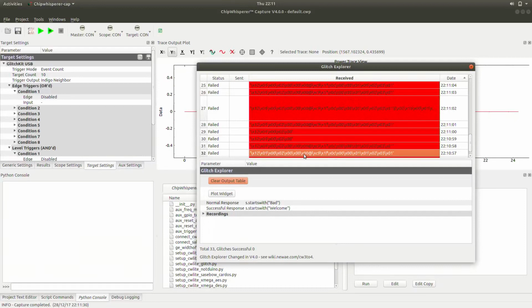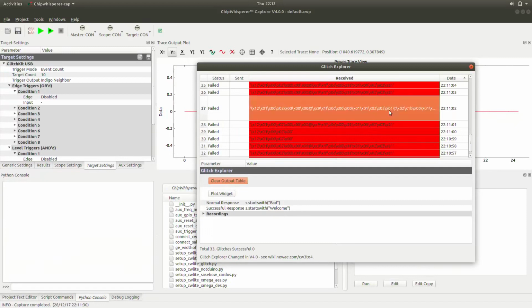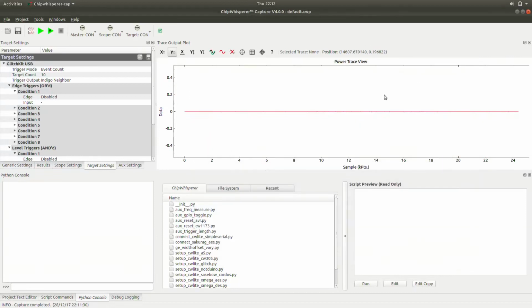So what you'll see here is we get a lot of responses that are the standard response. They're what we expect to come out of it. It's trying to read 18 bytes, that's hex 12, of USB descriptor. It reads 18 bytes, it gets 18 bytes. But this one here appears to have got significantly more data. And so on a previous run earlier today, as Kate said, this is simulated because it is not as quick as that when you actually run it.